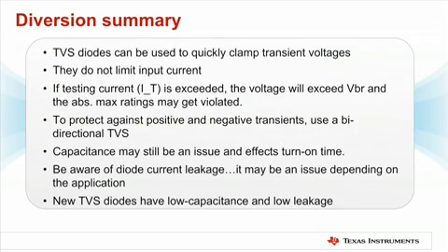A downside to this strategy is that the breakdown voltage for a diode increases as the current flowing through the diode increases, and this scheme alone has no way of limiting current. Bidirectional TVS diodes can be helpful, but most have symmetrical breakdown voltages, so systems with non-symmetrical supply rails will have to use two unidirectional TVS diodes.